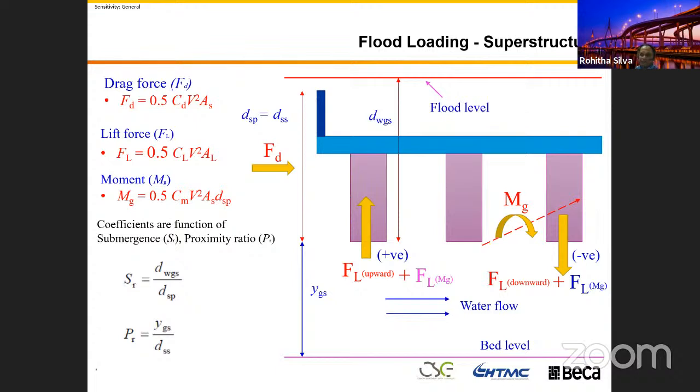We know the downward force is not going to govern in the bridge design because we design the bridge for traffic load. But this uplift is quite critical.